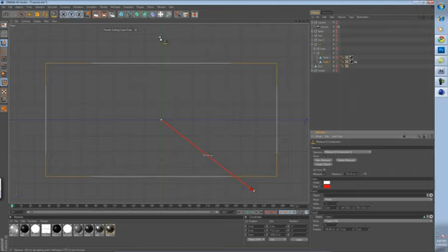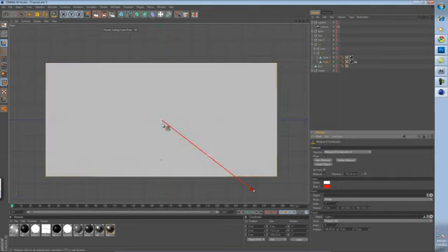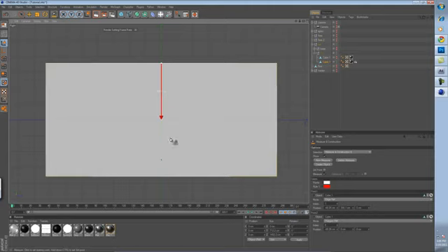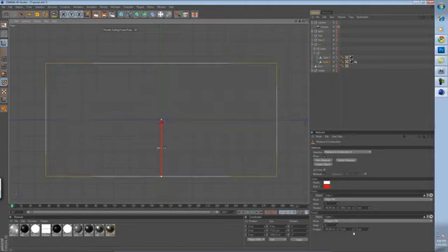Well, since we're only looking at the y and the z axis, right now the x value of these points is of no consequence. All you have to do is take a look at the y and the z, and make sure that they're both 0, 0. That way you know for a fact that it's centered on your plane, and then all I have to do is click over here, snap to this edge, and it snaps, and then it gives me a measurement. So I can control point 1 by clicking anywhere, and point 2 is just controlled over here.